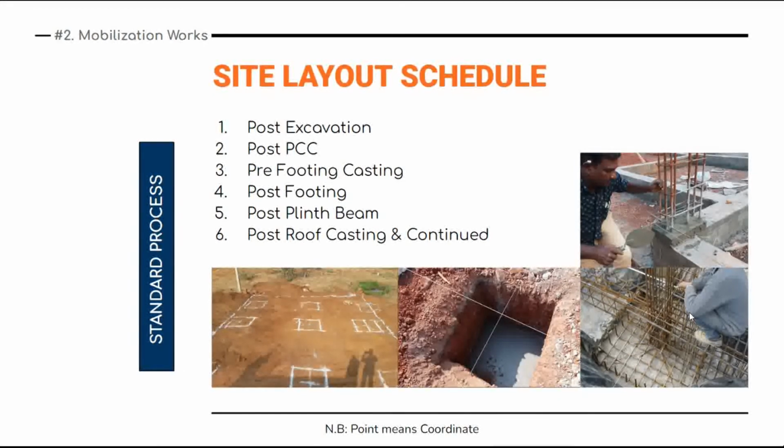Then after the footing, the plinth beam, again before the start, during the starter casting, you have to check the layout again, because after this everything is going to be identical.